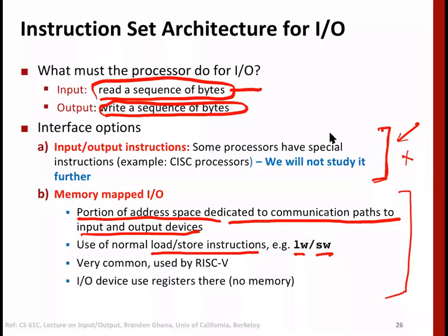Simple. Rather than using 0000 to FFFF, all the address space, for memory, part of it will be reserved for IO. So when we say load word from a location corresponding to IO, we will read whatever input that device has. Similarly, suppose a printer is mapped to one of those locations reserved for IO; when we say store word, it will go to the printer in some sense.